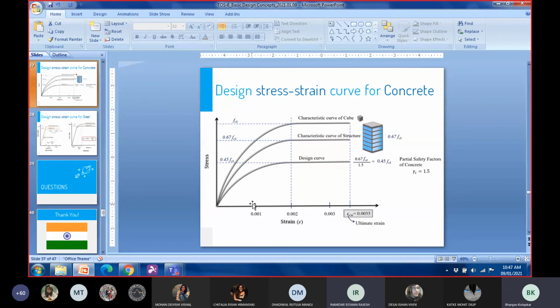Okay. Ideally, what you say is correct. And on the same lines, if it's a very special structure, what is called performance-based design is done, which is again a design philosophy. Like we have working stress, ultimate strength, limit state. There's another one called performance-based design, which is based on the performance of the material in that particular member. That's a very involved way of designing structures. For ghar ki structures, you don't need it.